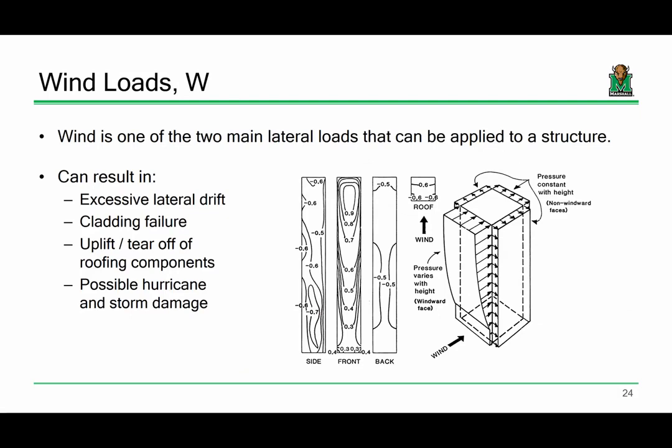So we'll start talking about wind loads. I think I went through this kind of quickly last time, so I want to take my time and go through it in a detailed fashion. So again, one of the reasons that lateral design is so complicated, at least with winds, is that wind pressures get larger the taller the building gets. So your wind pressure and your design for wind is a function of height. In fact, the height of a building can dictate what the building even looks like from square one.